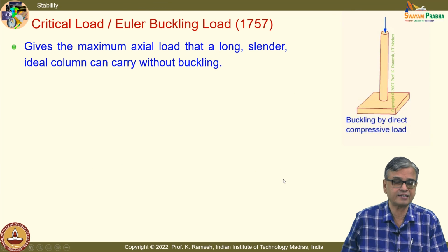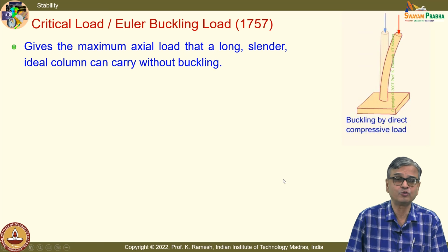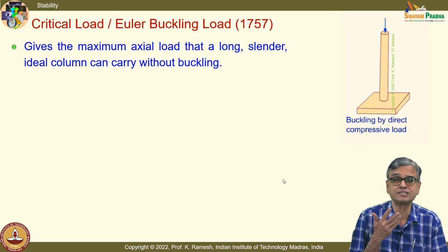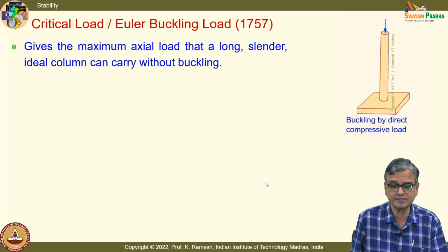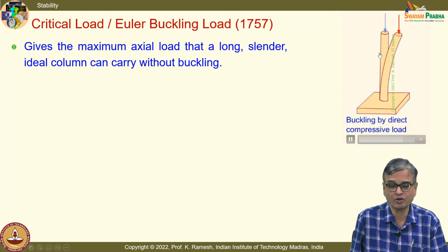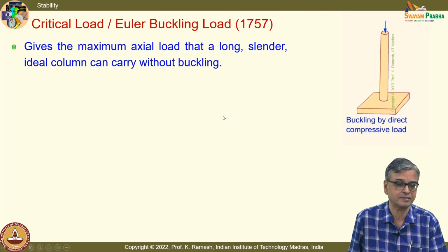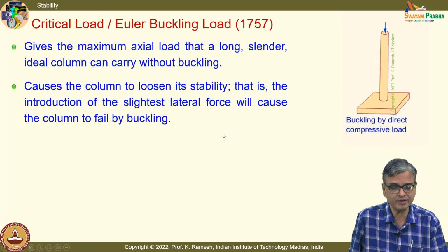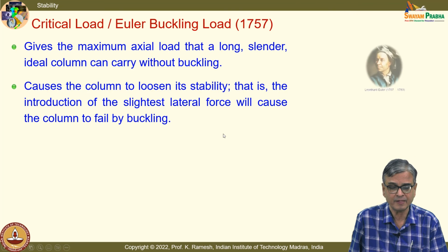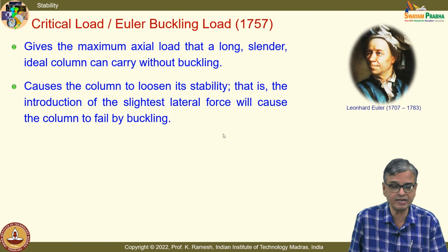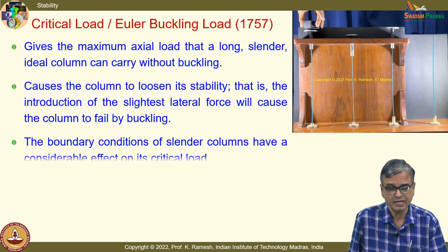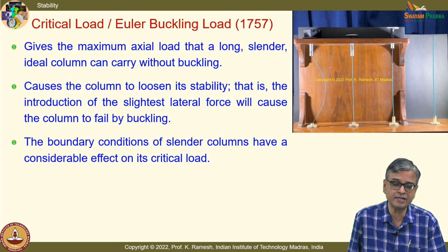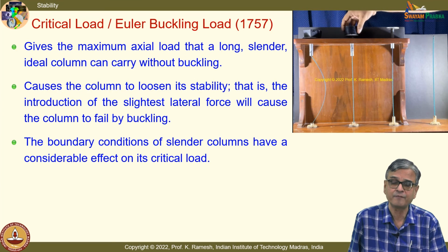Then we said that when you don't have a warning, any failure is difficult to handle. So, one of the functional failure modes is a column that suddenly buckles. Okay, there is no material separation, but it suddenly buckles, and we have seen that this was developed by Euler in 1757, and buckling is one aspect where we have to analyze on a deformed coordinate system.